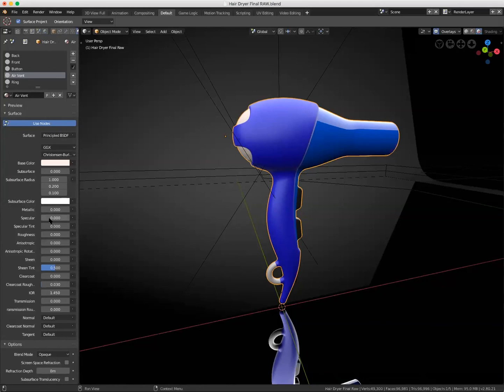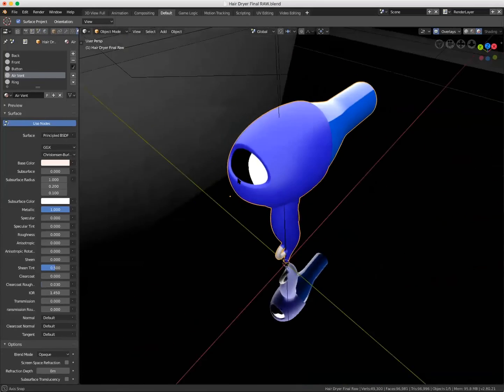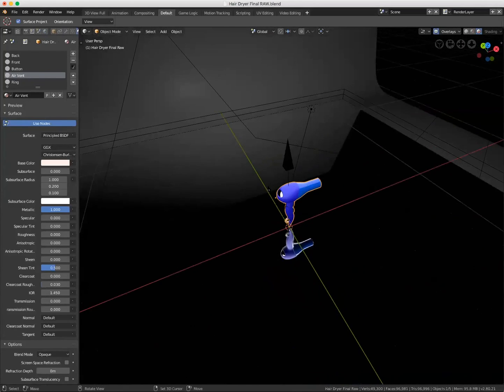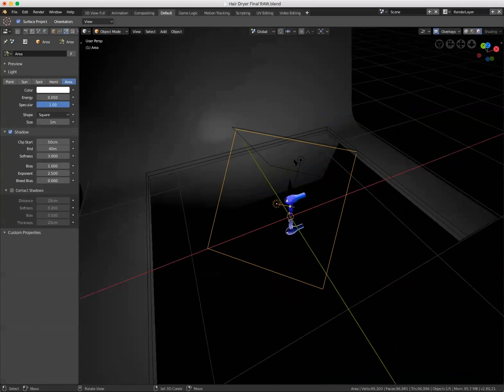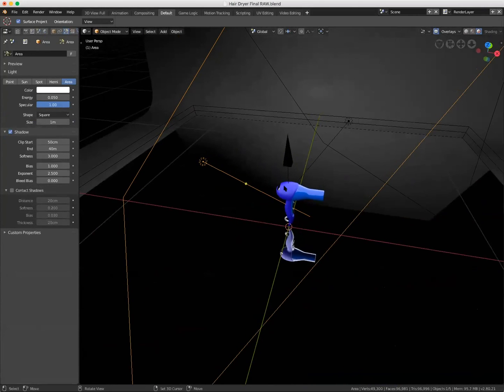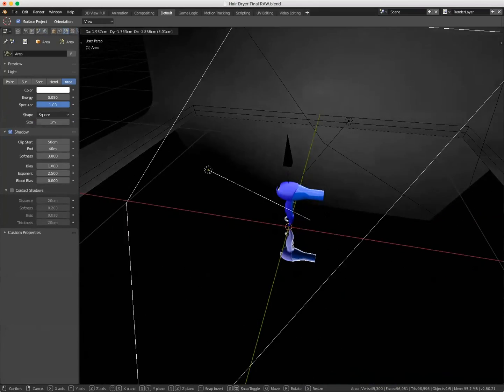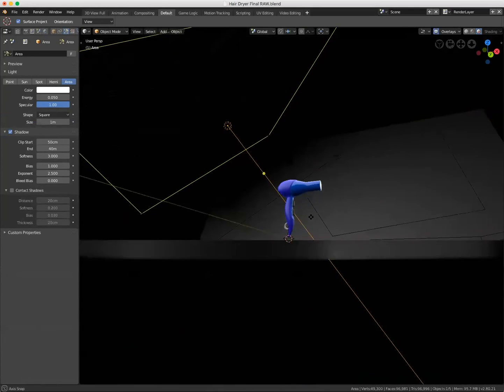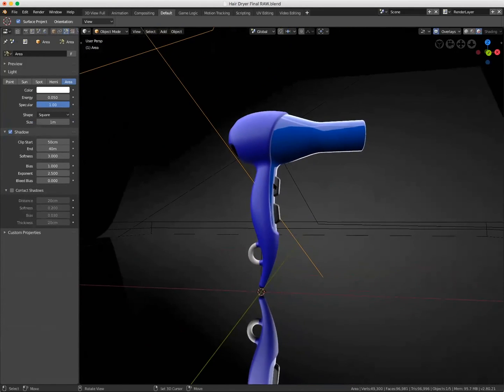So instead of specular, which is just plastic, we turn on metallic. And if we then rotate the view, you can see that it shows a reflection of my environment. And even these lights, which I placed, I will select them for a moment so you understand how this works. If I move them around, you see even the illumination and the reflection on the object changes. So this is just a very quick introduction, obviously.